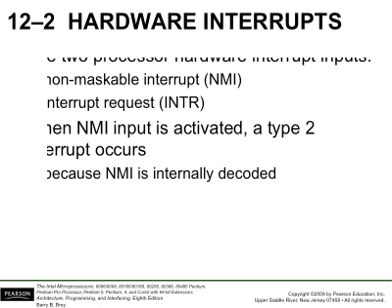So that's the case where this NMI will be very useful. Using this NMI, we can notify the microprocessor that this complete power outage is going to occur in the near future. So the microprocessor should do something special, which is to save the status of the work to a flash storage or to disk, so that it won't cause any drastic effects. For example, you don't want your important data to be lost completely.